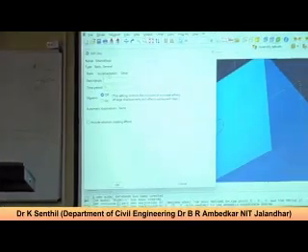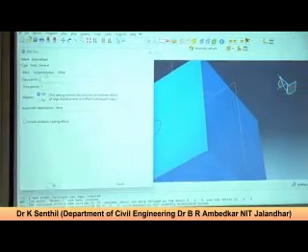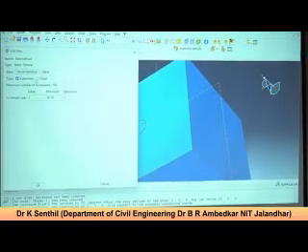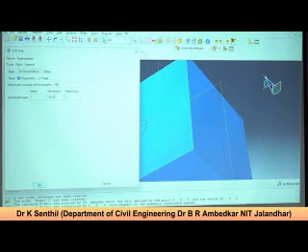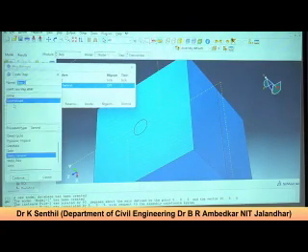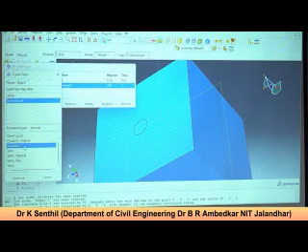So this is the time increments, delta t, how the increment actually takes place. You can keep either automatic or fixed, and sometimes you have to study this carefully, because how much time your earthquake motions or the lateral load actually takes place, accordingly you have to define the time steps. Because it's frequency related, whatever frequency you want in your simulation, that you will get. So now the external load is created, and now you can go to the geostatic for the gravitational force in the pile as well as the soil.